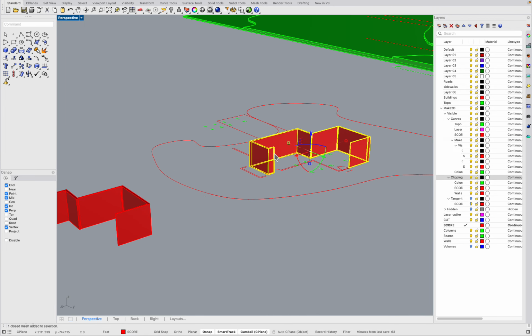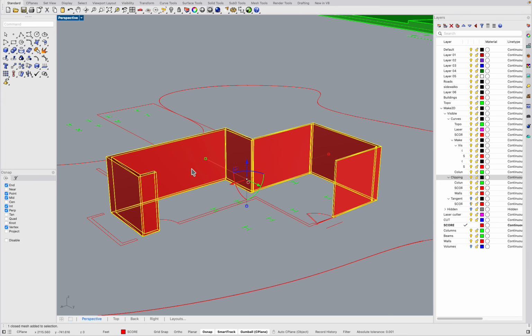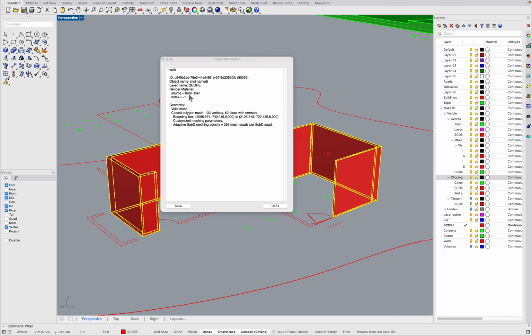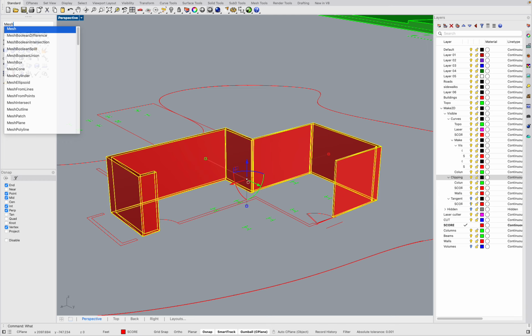And keep in mind, especially if it's a really simple shape, they can look the exact same. So, excuse me, the triangle doesn't always come up. So sometimes you do have to type in what and go, hey, is this a valid mesh? That's a valid mesh. So actually mesh repair for this one, it should probably be okay now.